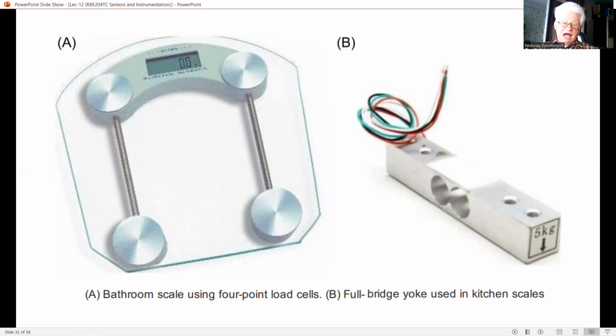and an extensive FEM analysis of such thin film piezoelectric accelerometers provides guidelines for the design of devices with specified properties. A different approach is followed in some publications, in which the PZT is deposited in a thick layer, typically near 50 micrometers, on an alumina substrate.